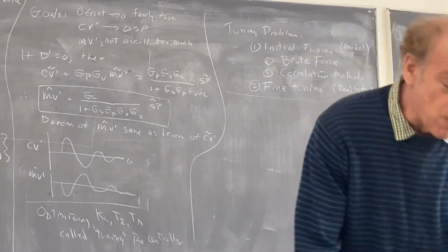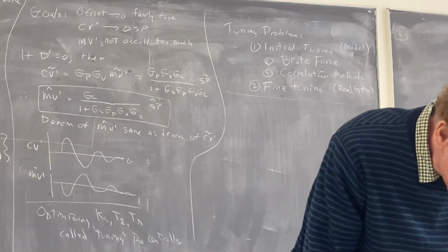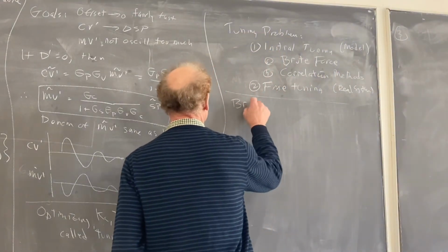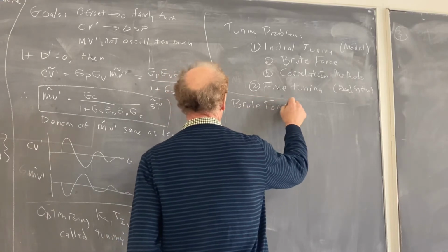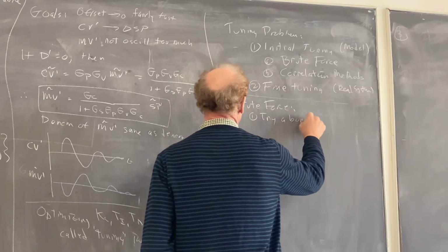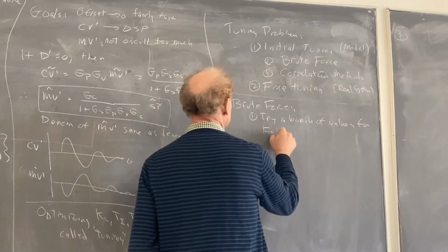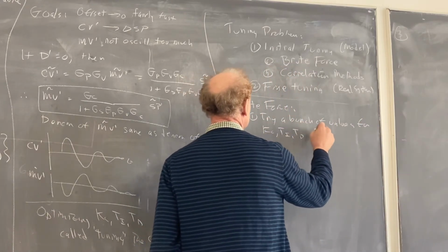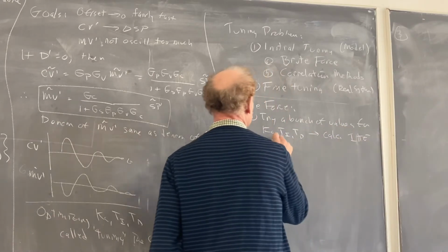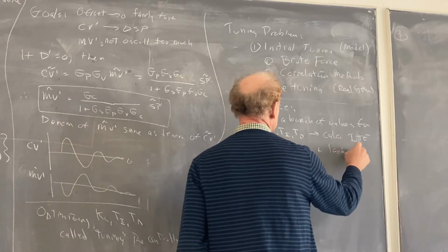So what does brute force mean? The idea of brute force is: try a bunch of values for KC, TI, TD, calculate the integral absolute error for each, and look at which is best.